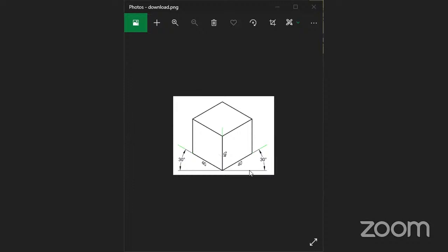And you can see that they made this 30 degrees, and here 30 degrees. This was supposed to be minus 30 degrees actually, because it's on this other side. Let's say this is the origin, and they made this 30 degrees, and this other side 30 degrees. So you can see that this is actually drawn with just lines, on 2D space, not a 3D object. But the way they represented it, it is being seen as a 3D object. They achieved this using isometric drawing.